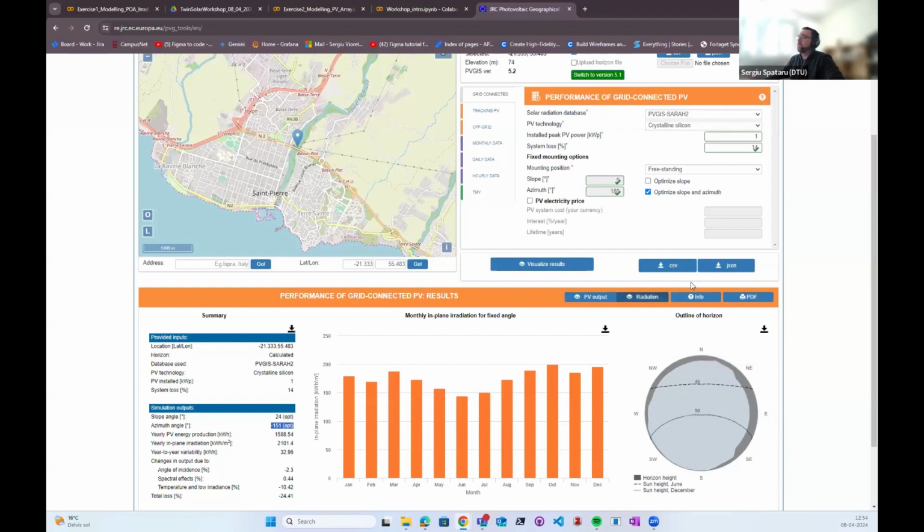In addition to that, the way PVGIS calculates the optimal orientation is based on data. It takes this TMY data set, runs it for all the possible tilts and azimuths, and calculates the numerical maximum of the insolation. Then you get a tilt and azimuth that gives you the maximum insolation based on data.